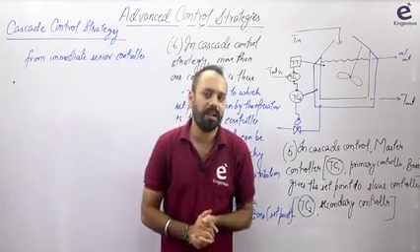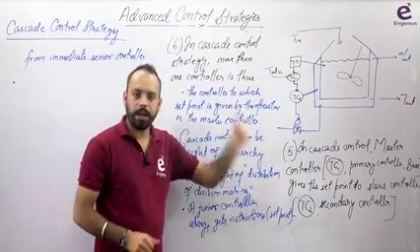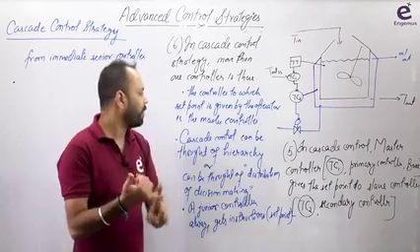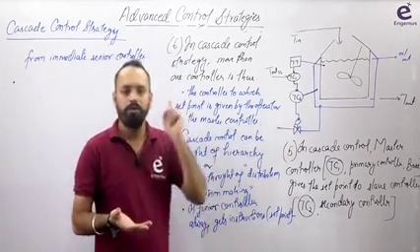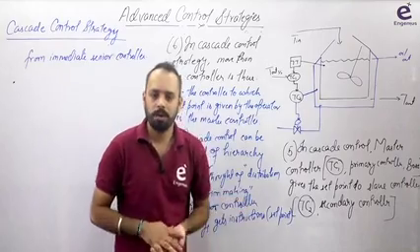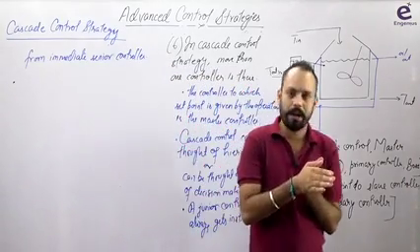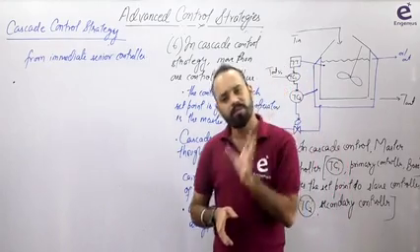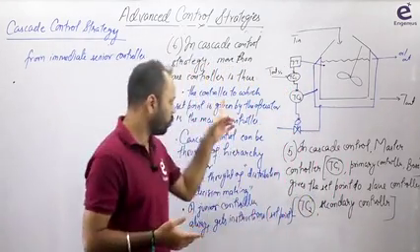Earlier, what was it deciding? Earlier, this TC1 was deciding what should be the jacket temperature. For that jacket temperature, what should be the flow rate. For that flow rate, what should be the valve opening. For that valve opening, what should be my output. So earlier, when there was only one feedback controller, all the decisions were taken by only one controller, TC1.